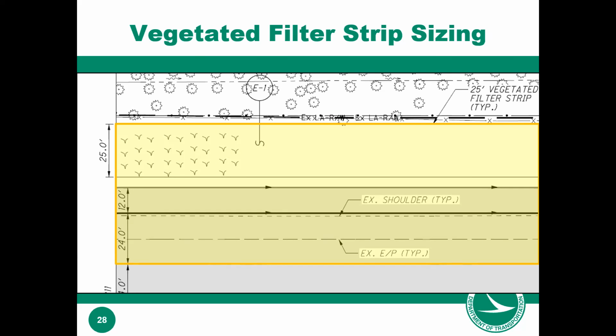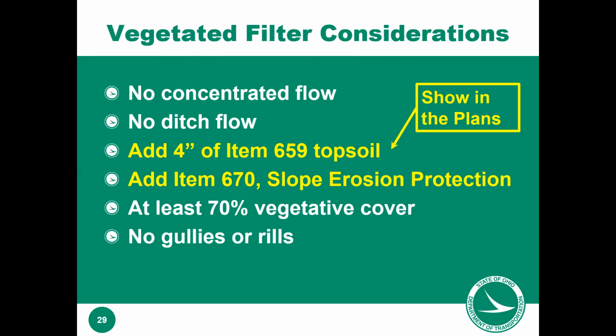And this is another weird thing that you have to get into the weeds a little bit on: ODOT does BMPs based on acres treated area. Ohio EPA does BMPs based on water quality volume. There's a lot of good reasons that both do it their way, but you're not looking at water quality volume as much for ODOT BMPs. You're looking at acres treated, and then it just has to meet these criteria, which simplifies a lot of transportation projects. But it can be confusing for people who go back and forth between a detention basin at a new gas station and a roadway BMP, going between water quality volume and acres. But acres are what matter here.